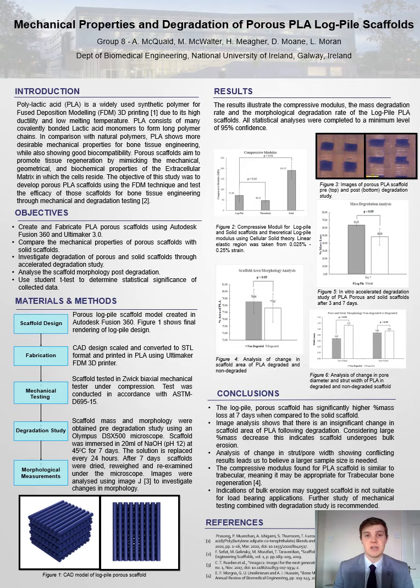The conclusion section of the poster. From the results, it was concluded that porosity has a significant impact on the scaffold mechanical strength. Porosity influences the degradation rate of the PLA. This is most likely due to the increased surface area of the log pile scaffolds. The large change in mass but insignificant change in PLA area suggests that the scaffold undergoes bulk erosion.